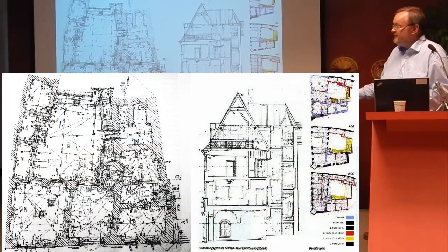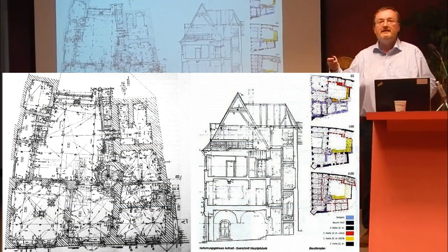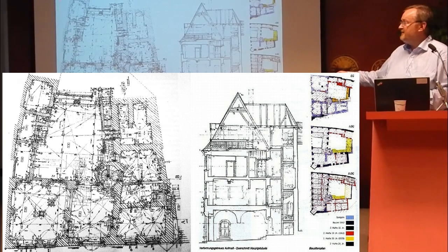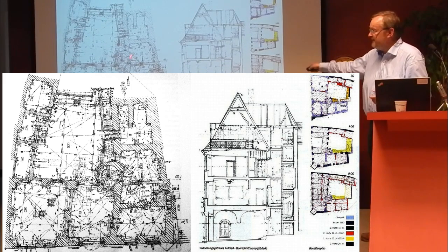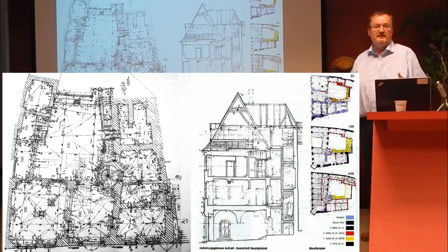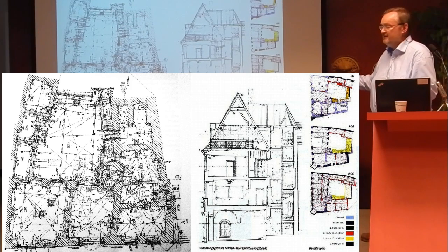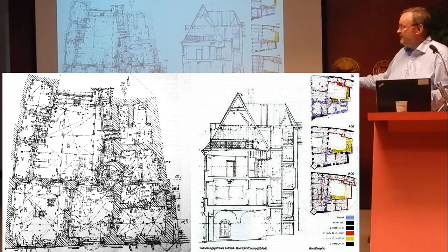The big work is to understand the building. And so we make a geometrical survey to get a plan of the building. But the survey must be very exact. It must follow all deformations. That's the principle, to understand the whole building correctly. That's a Renaissance building in another place. We have all deformations which the building has undergone over the times in the plan of the existing building.